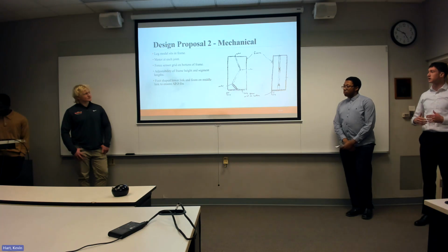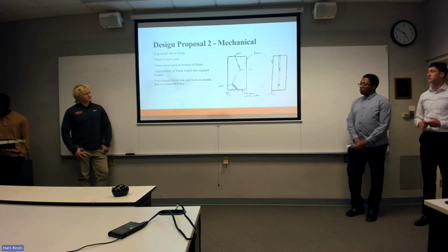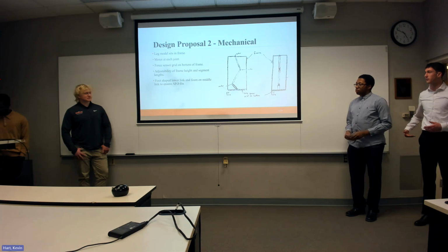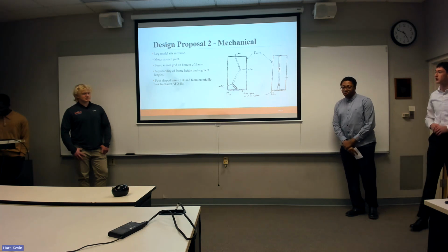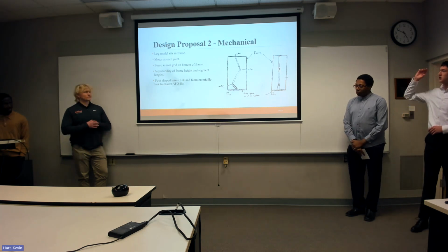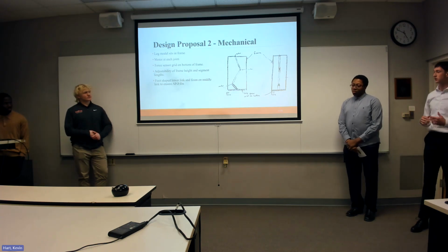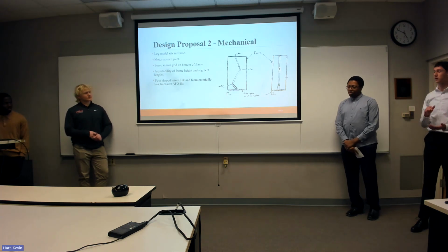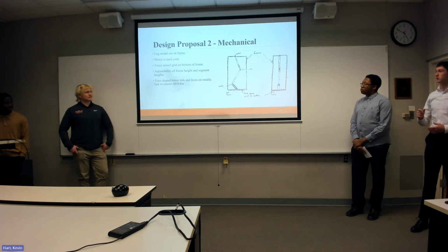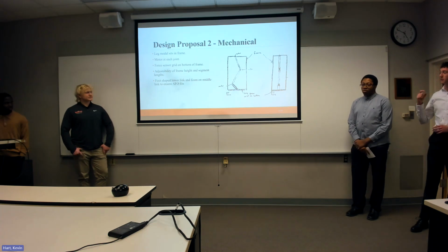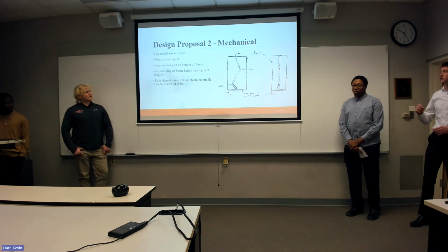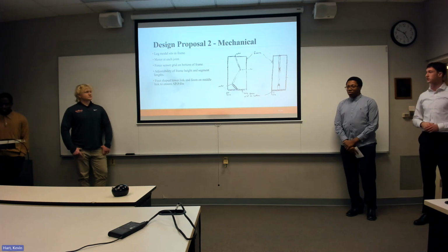And then it would be necessary to make not only the segments adjustable, but also the frame, so that we can get the correct hip height from the ground. And then the shape of the top link wouldn't matter too much. The bottom link would most likely want to be shaped like a foot in order to properly fit in the orthosis, along with the possibility of adding foam to the lower half of the middle segment for the same reason.